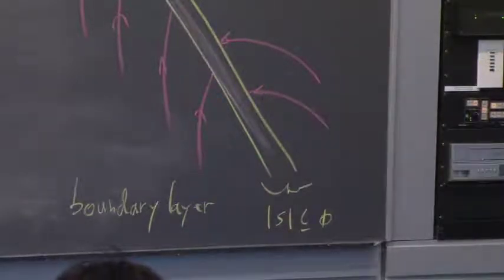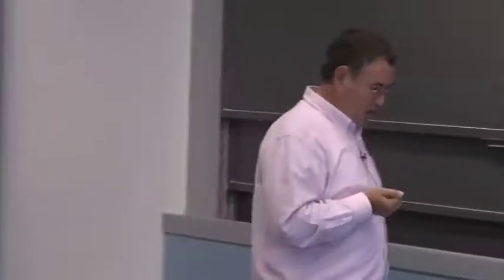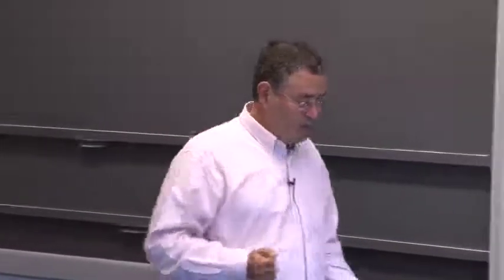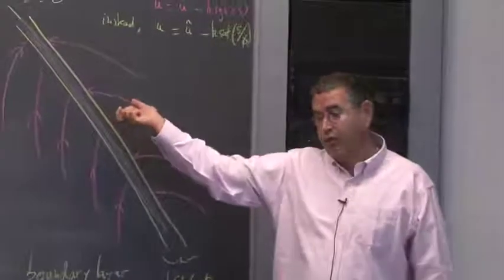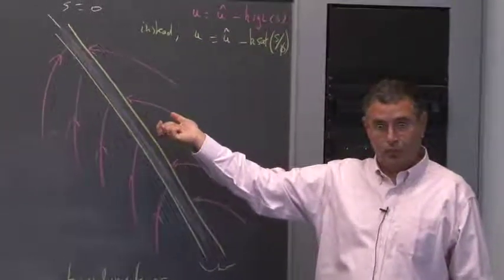So basically, before we were reaching s equals 0 in finite time and then stayed on it and slid along it. Now we're reaching this boundary layer in finite time, and then staying in it. Which gets back to your question. Once we know that we stay in it, it means that by definition s is less than phi.